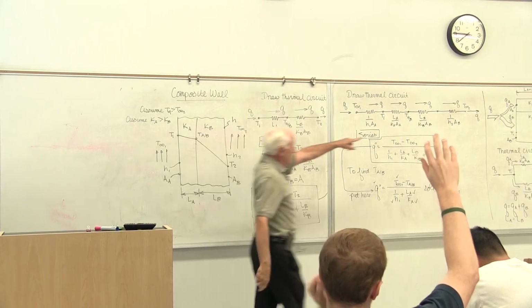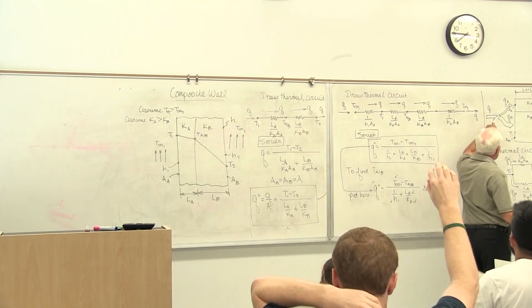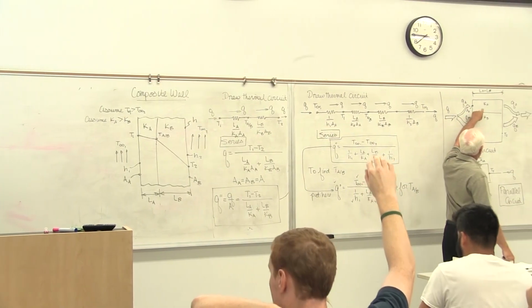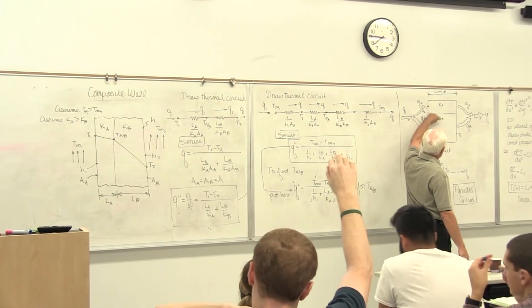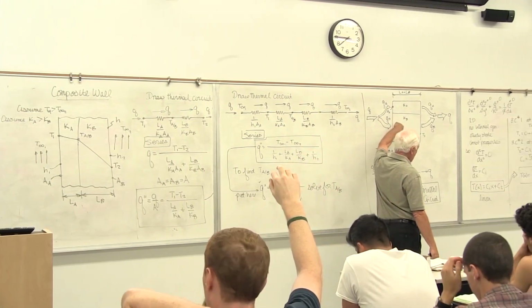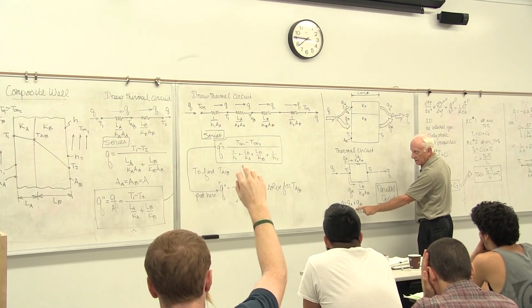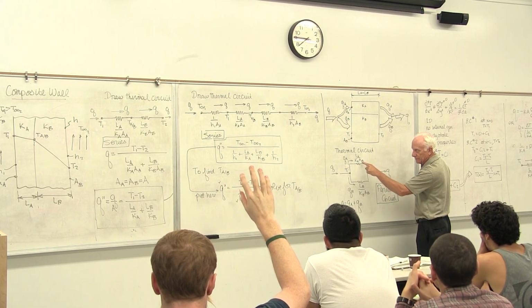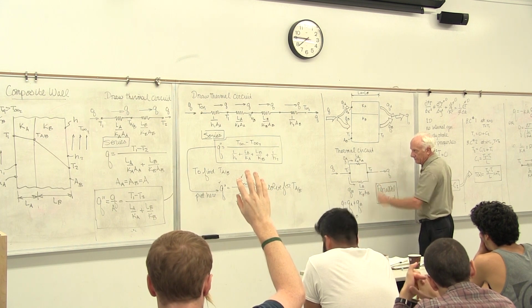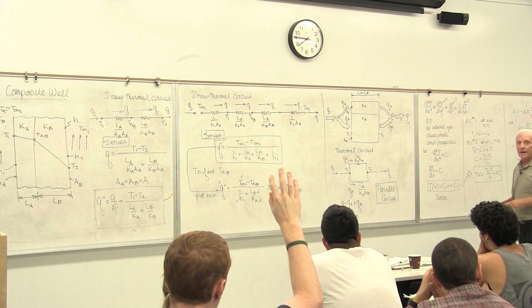Some of the heat from outside to inside goes through the glass blocks. Some goes through the concrete wall. The total is, add them both together. They both have the same thickness, but their areas and their Ks are different. So that would be a wall like that.